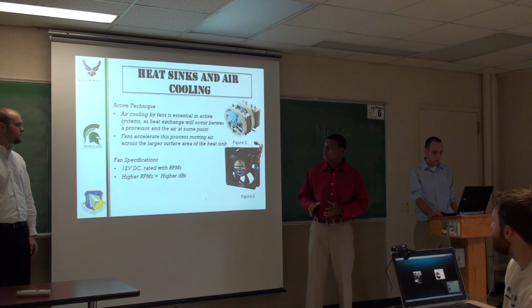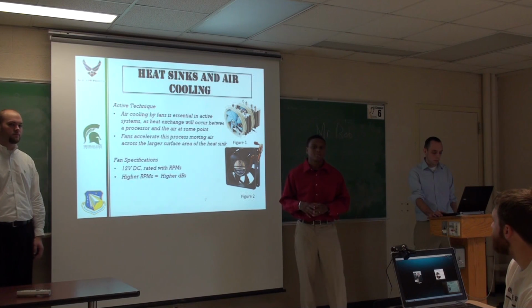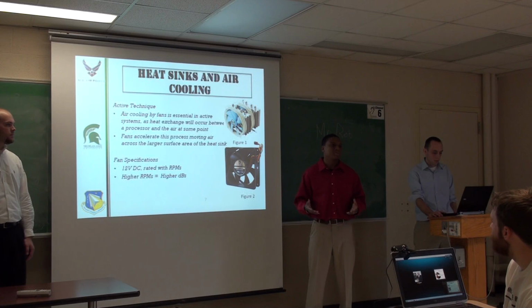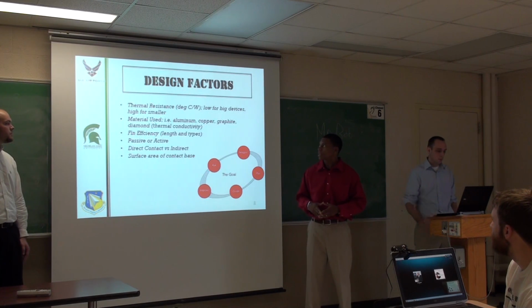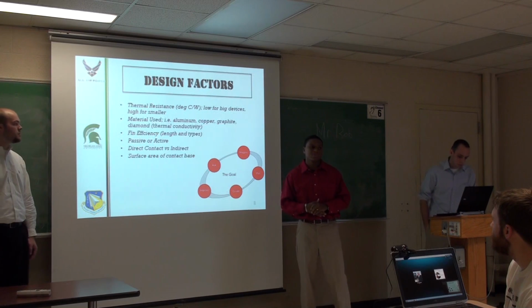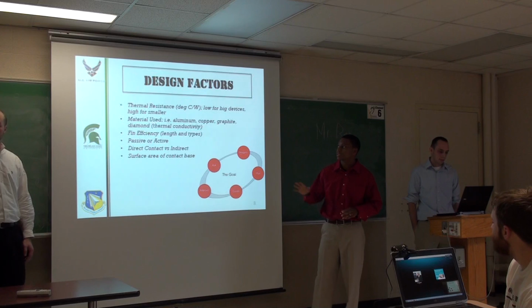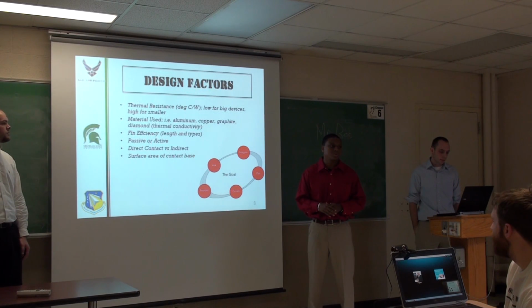If you can use a bigger or a greater diameter fan that will generate the same amount of airflow but have less dB, it'll be quieter. So some of the design factors when you want to pick out a heat sink for your own personal applications, you've got to take into account the thermal resistance, which is given in degrees per watt.